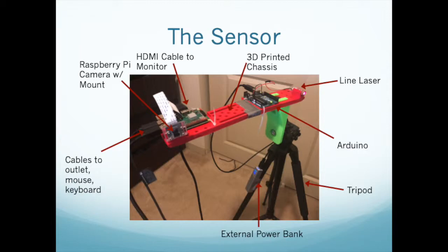Since the pieces were printed separately and did not fit together well, I was unable to epoxy them together, and so had to use duct tape. This did the job as the two pieces were relatively rigidly connected. My line laser did not fit in the hole, even though I adjusted the size in the CAD file, so I had to file out the hole and eventually just cut off the top. After adjusting the laser direction using laser alignment image.py, I made sure the line laser was held in place by using hot glue and more duct tape.